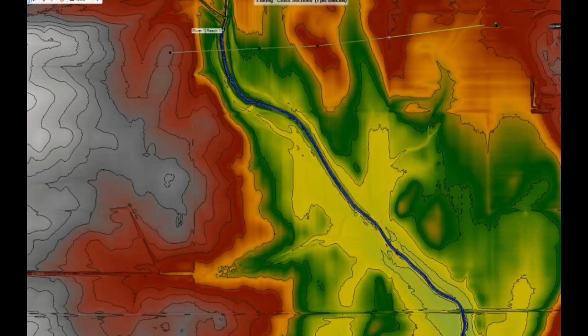When we talk about 1D river modeling, everything starts with cross sections, and drawing cross sections sounds simple until you actually try to do it properly. In most workflows, you have to manually draw each cross section perpendicular to the river center line. That means checking angles, adjusting spacings, and constantly zooming in and out to make sure you're not introducing geometric errors.